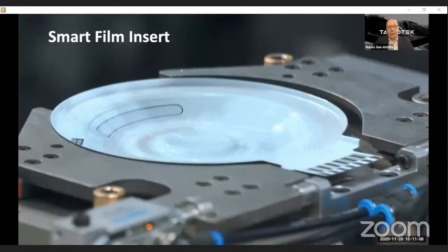The film insert, as seen in the picture, is in a 3D shape before molding, not at a flat level. It is recommended to form this film before the molding to achieve electrical, aesthetic, and dimensional stability. The term insert, as in feeding into a tool, is not from a feeder. Typically, it is done by a robot, and that's why the film will be placed into a tool as an insert.